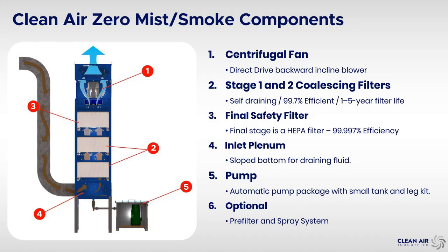So if you've ever seen a tube mill that bends a piece of metal up, welds it, and then directly dunks it into an oil bath or some kind of cooling system, you're getting oil mist and weld smoke all at the same time. We have a spray system that we can put in that sprays water on the bottom of that first filter, and it keeps that filter moist.